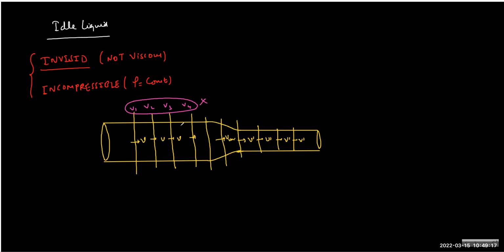So imagine that you say, no, sir, I want a situation in which V1, V2, V3, V4 is possible. That is possible, but in such a scenario, the streamline concept will be broken down, and now the flow will become turbulent. That is exactly the case of turbulence. In turbulence, the velocity field gets distorted in a way. There is no uniqueness in the velocity distribution in space.